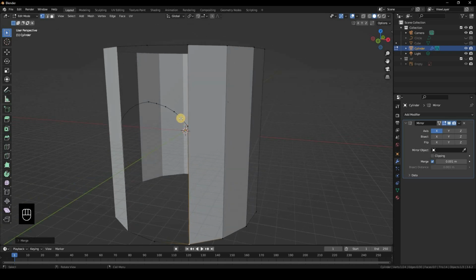The next thing we can do is, there are 1, 2, 3, 4, 5 and 6 vertices, so this one is easy. I'll just combine it with over here and then press F. But these three will require a loop cut, so I'll go ahead and add in Control R and add a loop cut around over here, and then we can add another loop cut that will join with these vertices, and Control R another loop cut that will combine with this one.